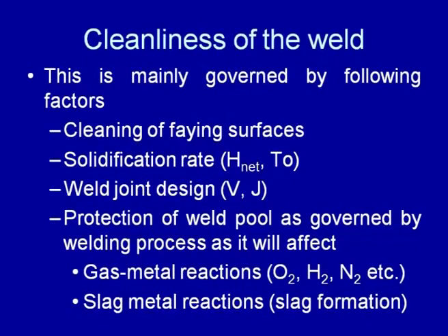So, as far as the cleanliness of the weld is concerned, this is mainly governed by how properly we are cleaning the faying surfaces of the base metal before welding, and the solidification rate. If the solidification rate is low, meaning the solidification time is long, then the impurities formed in the form of slag in the weld metal will have enough time to come up to the surface and get removed.